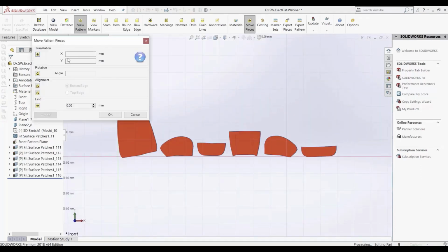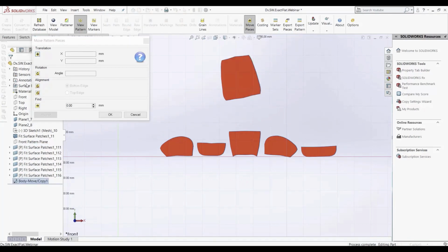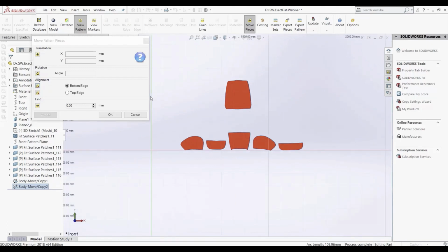The beauty of working from 3D to 2D is we have automatic pattern associations. We're just going to move these pieces in place. Now, if we did not have pattern associations, it would be very difficult to align these pieces in an orientation which is suitable for doing the pattern design work. And what we'd have to do, and this is common with other programs, is select pieces manually, like this, and drag them around. Well, let's just get this piece again here. Okay, there we go. We'd have to move them and eyeball them into place.